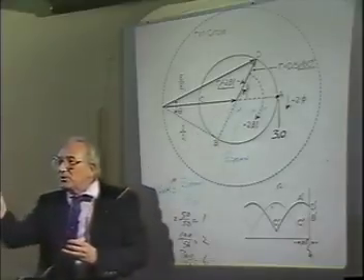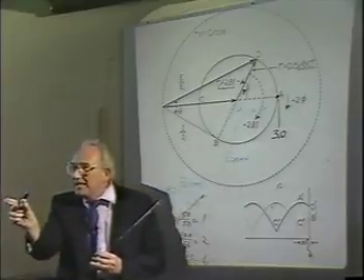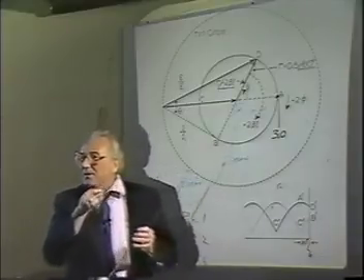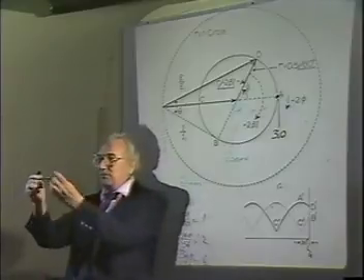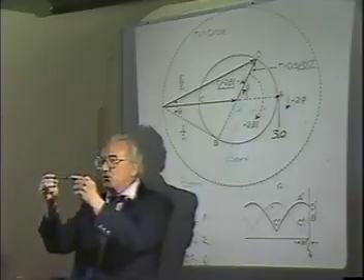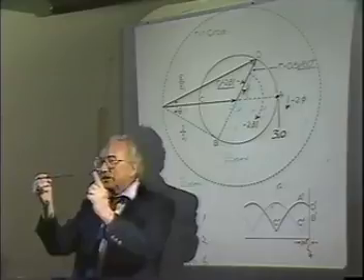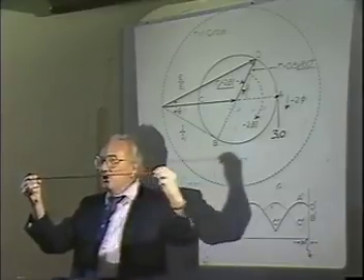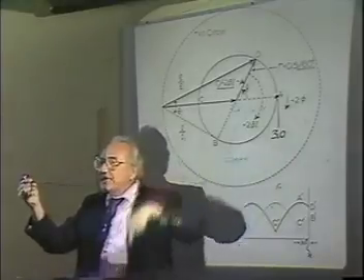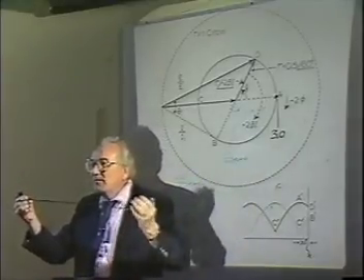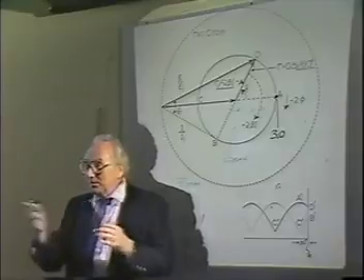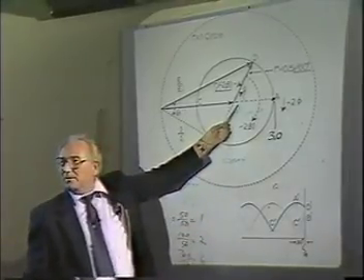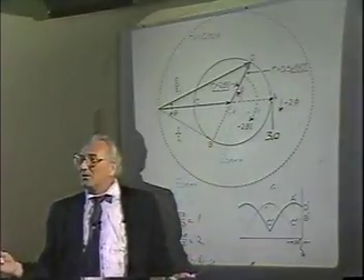Remember what happened when we put a 3 dB pad, another 3 dB pad, another 3 dB pad on the transmission line? What happened looking into all these pads? So we have 3 dB, right? We look in here, we saw a 3-to-1 mismatch. Went out to 6 dB, 10 dB. We looked in here and saw 1.22 mismatch. More attenuation. Looking in here, you see less and less VSWR, right? Where will it eventually turn out? It'll eventually be at the center of the chart, won't it? You don't see it because there's so much isolation on the line.